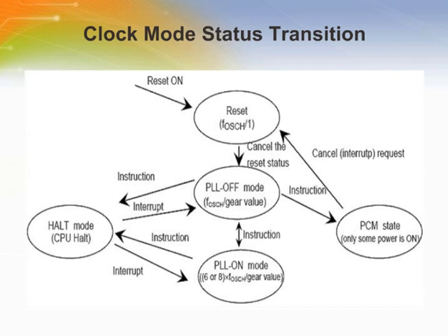The clock controller is a circuit that controls all the clocks in the MCU. It has the following features. By using a clock multiplication circuit, PLL, the clock controller supplies a clock of up to 200 MHz to the CPU. A multiplier factor of 1, 6, or 8 can be dynamically selected. The clock gear contributes to the reduction of current consumption. Write access to the registers inside the clock controller is disallowed. State transitions of the clock operation modes are as follows.